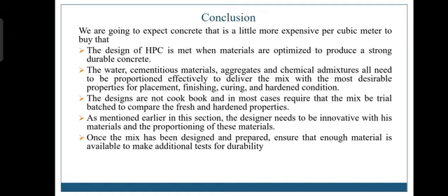The water, cementitious materials, aggregates, and chemical admixtures all need to be proportioned effectively to deliver a mix with the most desirable properties for placement, finishing, curing, and hardened condition. The design is not a cookbook, and in most cases requires that the mix be trial based to compare the fresh and hardened properties.